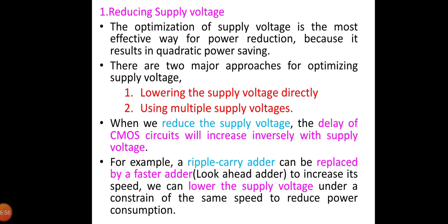Since the speed requirements for the adder, comparator and latch have decreased from 25 nanoseconds to 50 nanoseconds, the voltage can be dropped from 5 volts to 2.9 volts, and that voltage doubles the delay. While the data path capacitance has increased by a factor of 2, the operating frequency has correspondingly decreased by a factor of 2. Unfortunately, there is also a slight increase in the total effective capacitance due to the extra routing and data multiplexing. This results in increased capacitance by a factor of 2.15.